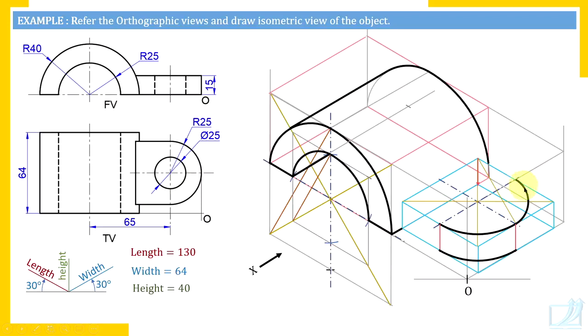Now when we draw this smaller arc, some portion of the smaller arc will be on the back side, and that's why hidden. So don't immediately draw this smaller arc dark on the lower surface. Now how to draw this smaller arc? Shift its center. Check here, the center. I've shifted it by a distance of 15 millimeters. All these pink colored lines are 15 millimeters vertically. So this point I have transferred 15 millimeters downwards. The center of the smaller arc I have transferred 15 millimeters downwards.